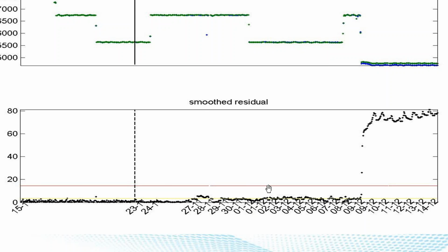But if we know the thickness of the wall of the pipe and we know how the corrosion progresses, we would be able to predict exactly where the leak would happen. But not just prediction, we would be able to show the operators that there's a defect that looks like inner corrosion due to the changes in the diameter, and alert in advance where it's happening and how much it's eating from the pipeline. This is the smaller version, but we can enhance each and every black dot here and see a non-decreasing pattern that will present that the escalation is progressing until a leak forms.